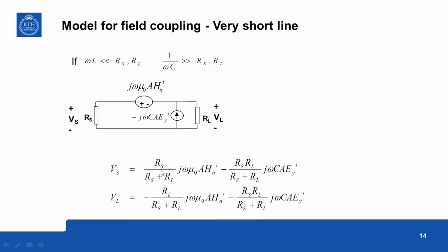As before, you can see that for the part related to the electric field, the induced EMF is the same on both ends, whereas for the magnetic field it is of opposite direction and of different value. So the general behavior is very similar to the near field crosstalk in terms of the characteristic of the voltages at both ends. That is the end of that module. Thank you.